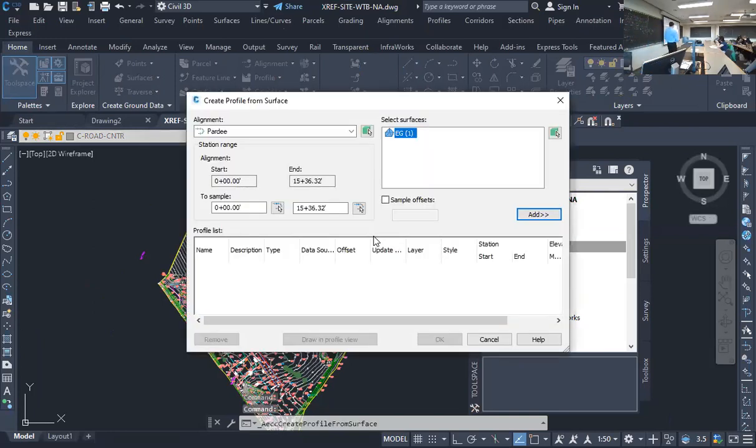It will bring up this dialog box. Remember, I created 2 roadways. Okay. My first one is part B. And you see how I have a surface. Okay. If you're missing something, it will bring this up, but it will either find the alignment or the surface. So both of them have to be there.